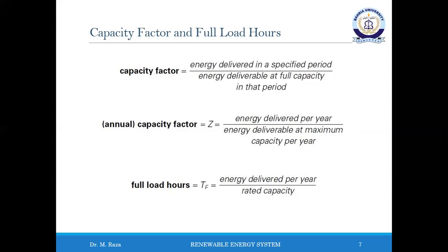Capacity factors are most frequently discussed in the case of electrical power generation, but the concept may be applied more widely. Note that solar devices can only capture sunshine in daytime. So if years include nighttime, then capacity factor is at most 50% even for a perfect device in an average day of 12 hours.